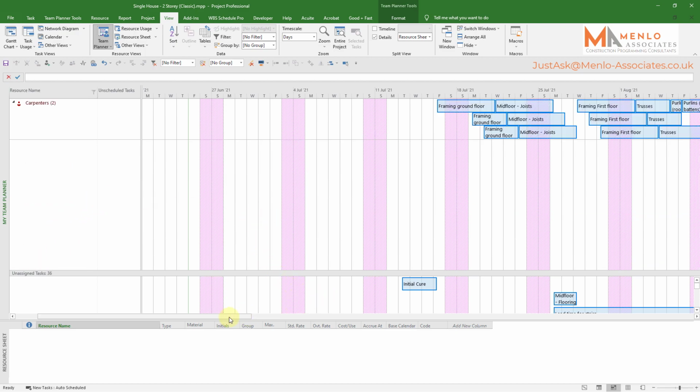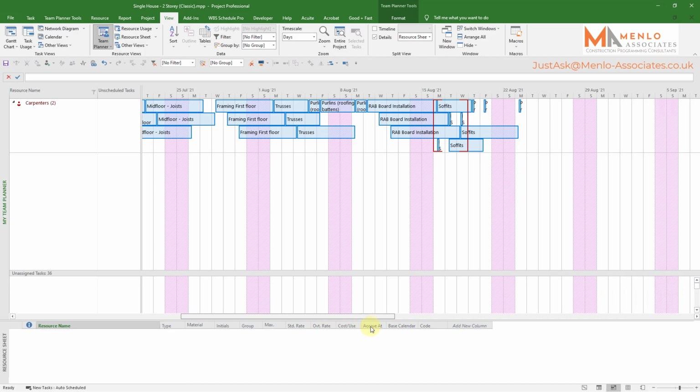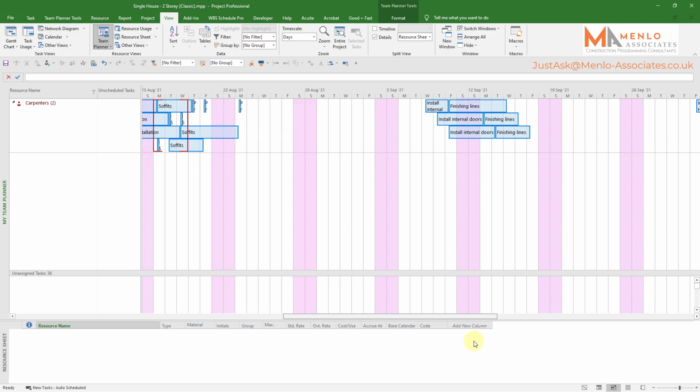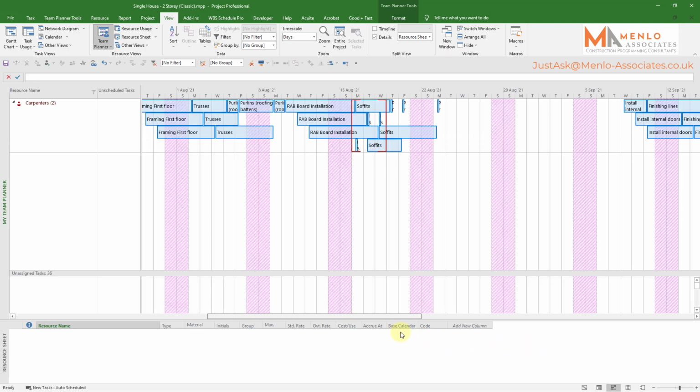and we look through the workload of the carpenters, we can see at its peak we need a maximum of 4 teams, but you can see there's quite a bit of porosity around this. We could actually say, okay, we don't need 4 teams. We could say look at reality. In order to meet the program without delaying anything, technically we need 4 teams, but you can see here I've got 3 days of work and what looks to be half a day's work.